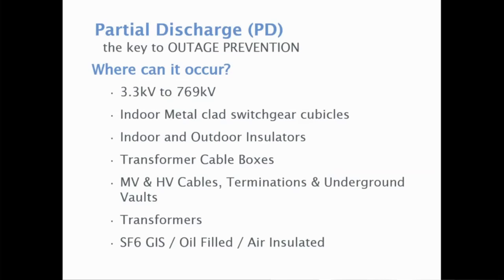So what is partial discharge? The Wikipedia definition is that it is a failure of part of the insulation to withstand the voltage applied to it. The entire insulation not withstanding the voltage would be a flashover, as we're familiar with. But if part of it can't withstand it and the rest of it can still withstand what's left, you get a flashover across part of the insulation. And it's an actual spark that you can see.